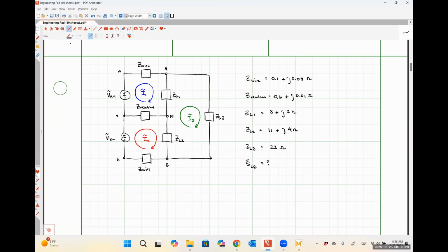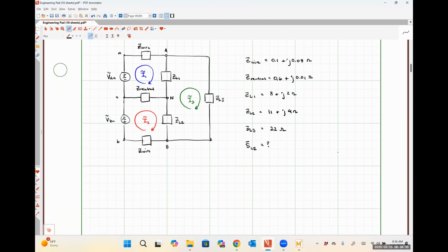Okay. So mesh analysis is setting up multiple different Kirchhoff's voltage law equations and then using that system of Kirchhoff's voltage law equations, you solve that system to get those mesh currents, okay? So you guys don't seem super familiar with it, so let's go through the steps, okay? I'm going to follow each of those currents around their clockwise path, starting from the bottom left-hand corner of each of those paths, and then I'm just going to keep going until I get back to where I started from, okay? So anytime that I see a voltage source, if I see the negative polarity terminal first, I'm going to give that voltage a minus sign.